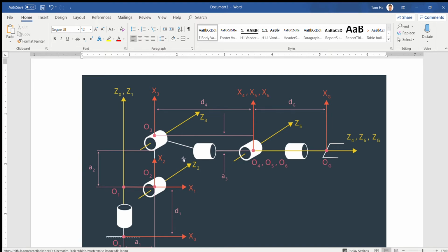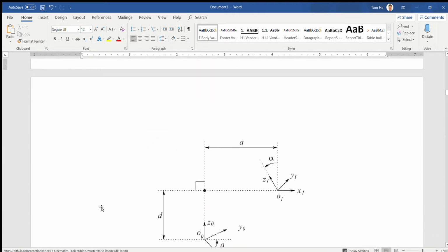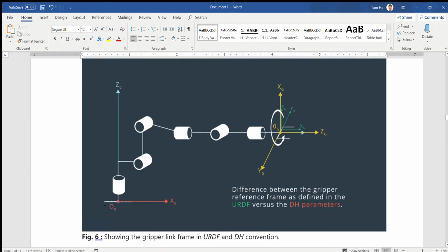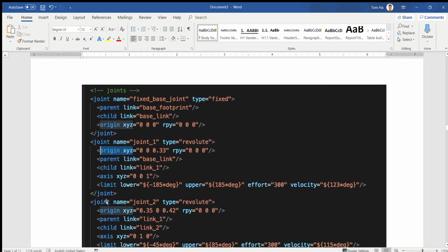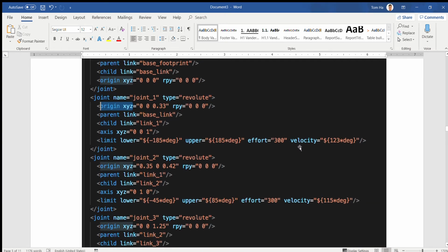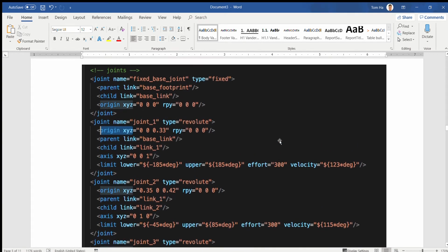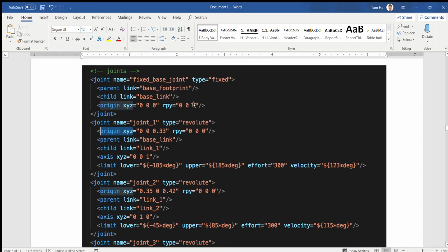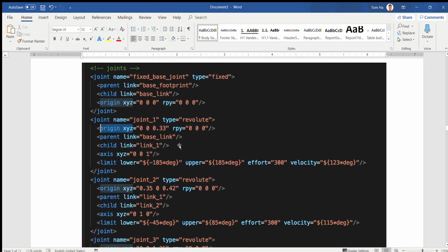And for example, if you see the problem with the Kinova arm or the UR10, you also have that file, and you can open it and check. Right, that's the URDF xacro file. For simulation, you can see the parameters, the numbers, how the length, how the x, y, z for each joint, and the distance between each frame.